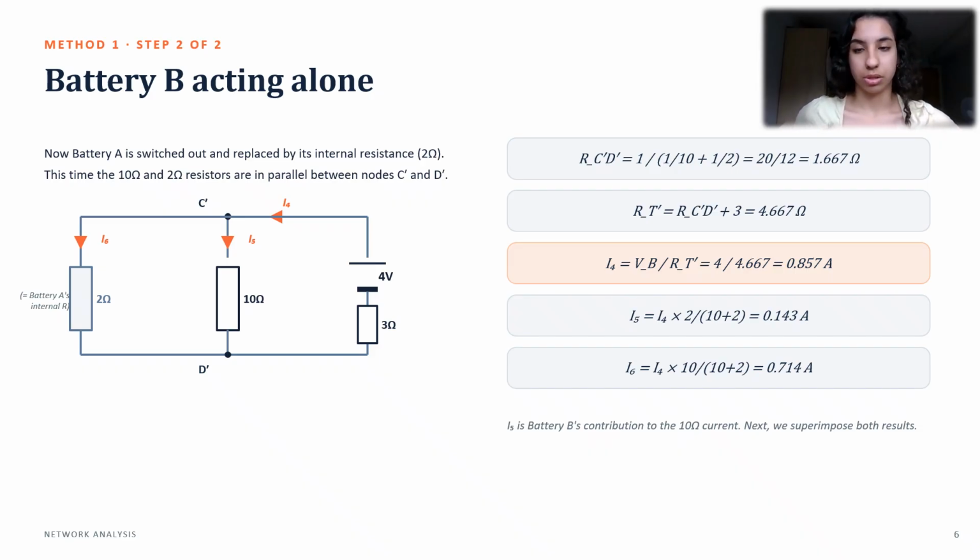We gave them these numbers just because we already had I1, I2, and I3, and we do not want to mix up. Okay, we do completely the same thing. We find the total resistance using the parallel circuit resistance formula. So we do 1 over 2 plus 1 over 10. The answer for that, we do 1 over that answer. We get 1.667. And then we get a simple circuit. We add that with 3. You get 4.667 ohms.